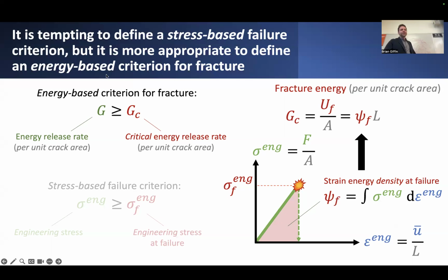And you can also go to the trouble of saying, if I know that this is the criterion for fracture, some energy-based criterion that says if I reach this particular limit, or maybe even exceed that limit, I know that basically the crack should extend, the crack should grow. So this is my criterion for crack extension, if you like.